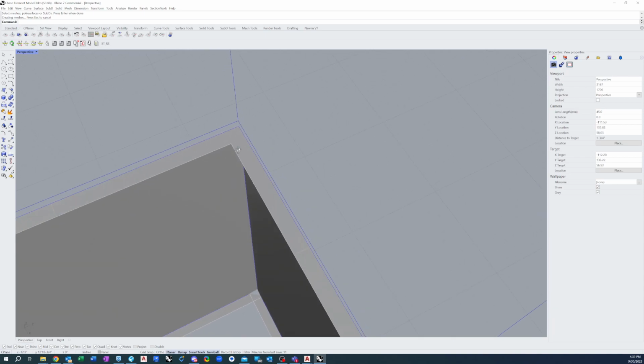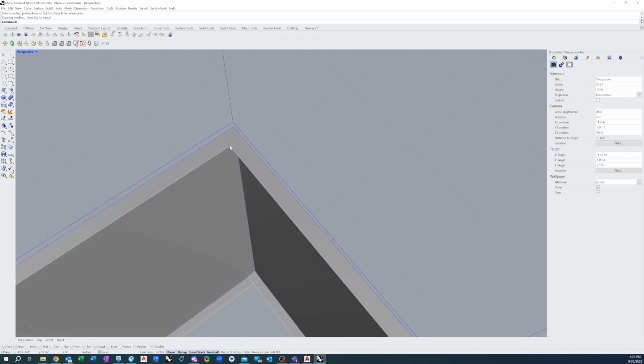Since this is going to be 2 pieces, you want to put a miter in it. So I'm going to draw a polyline for a cut line right here, and then do the split command. Split, select objects to split, this one, cutting objects, the middle. Bam. So now it's 2 tabs.